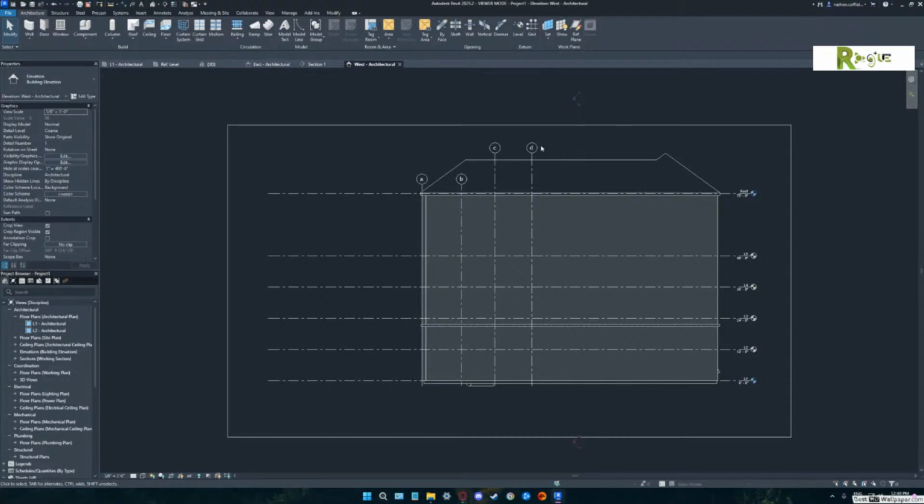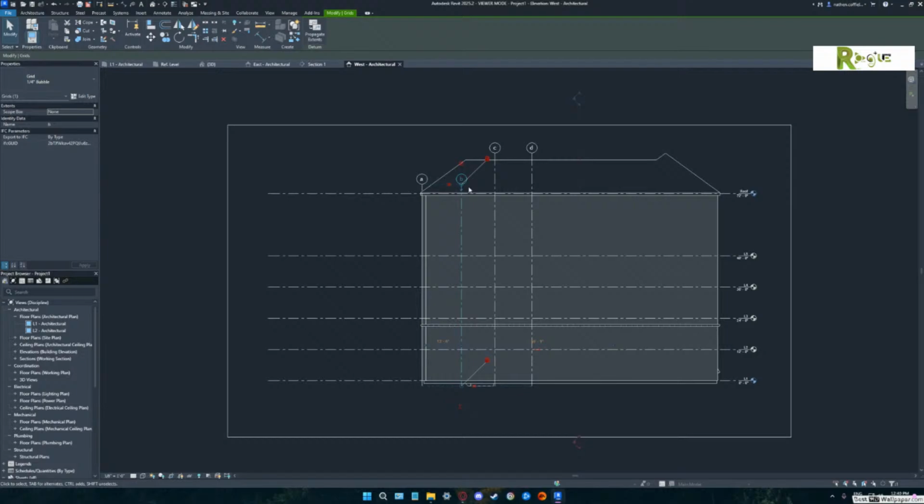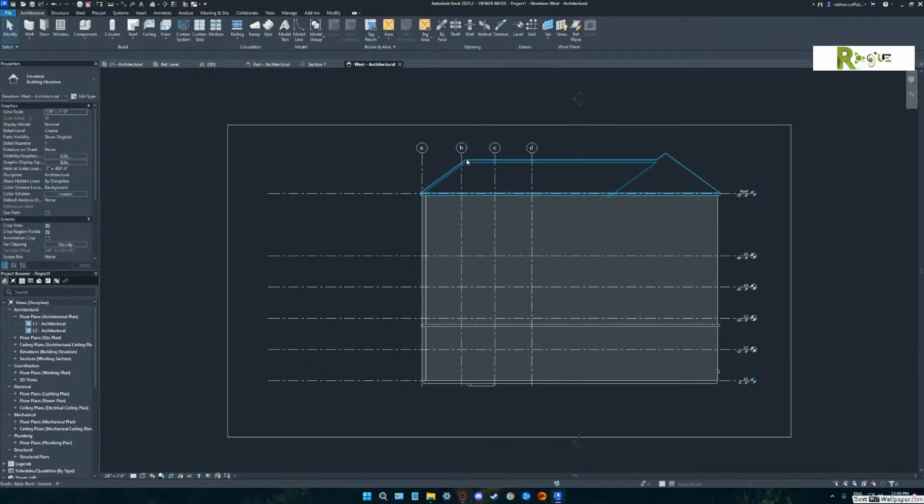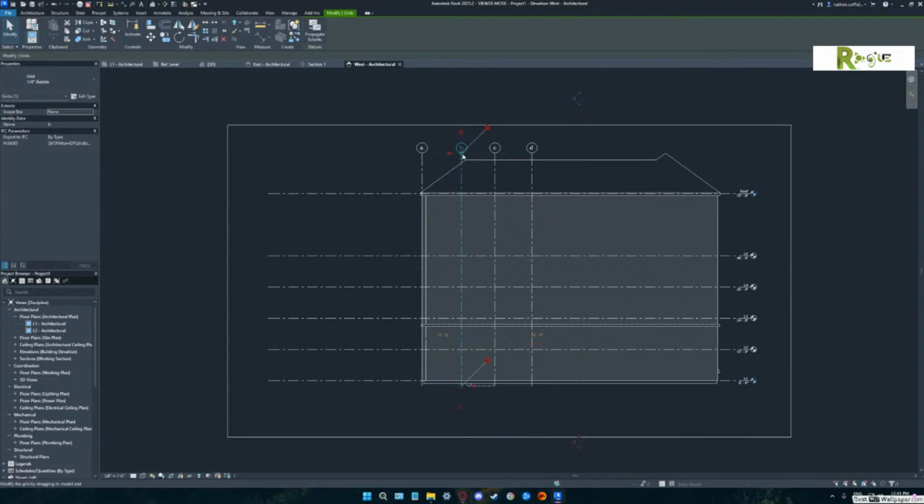Now that A and that B, we can fix by picking it. Pick the grid line. There's a circle at the top, right below the letter B. Drag that till it lines up with the others. Now drag it a little bit more and you'll see all of those are joined together. Once again, I'm trying to show you that Revit helps you out with a lot of things if you'll let it. And that's exactly what does it.